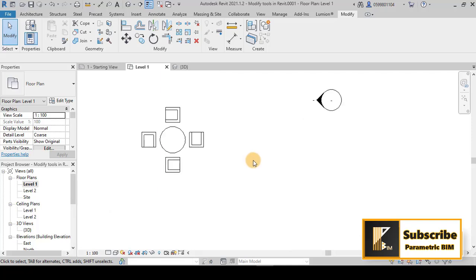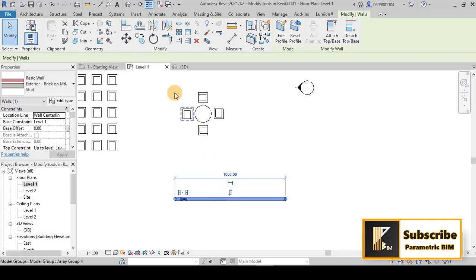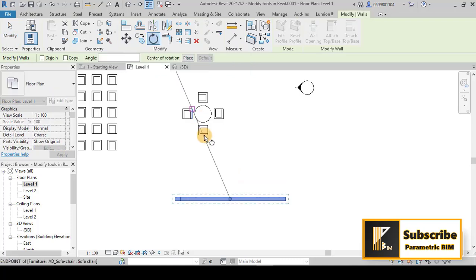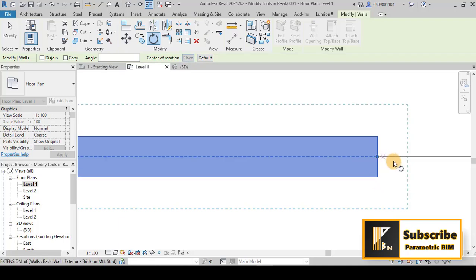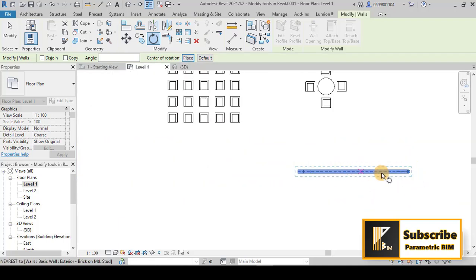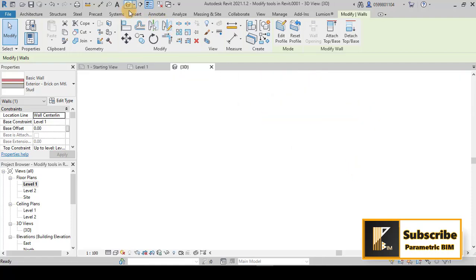Maybe also you have, for example, this wall and you want to rotate it maybe 30 degrees or something like that. You can click now, but you don't want to rotate it from the center line, you want to rotate it from this base point. So you can place now the base point to this point or this point, and then start rotating by 30 degrees. It will be rotated like that.